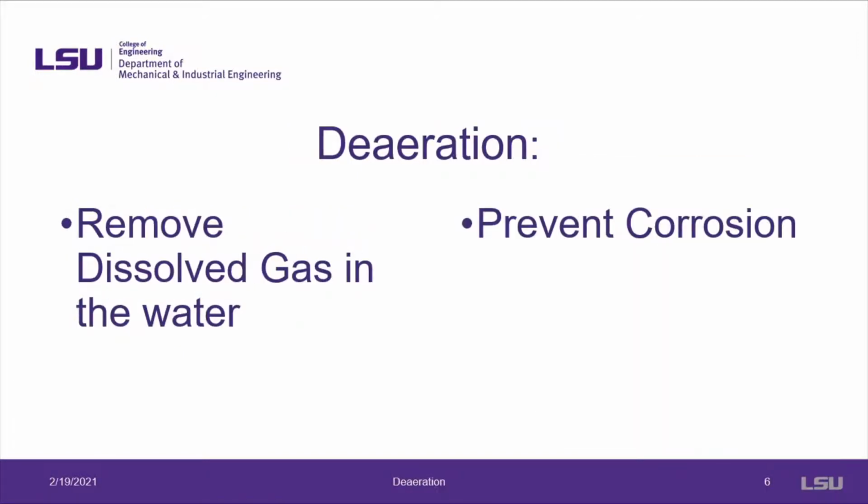The water leaving the demineralization system contains dissolved oxygen that is highly corrosive to the tubes of the boiler and the pipe connecting the boiler to the deaerator. Deaerators are used to remove this highly corrosive oxygen before it enters the boiler. The three main types of deaerators are tray type, spray type, and vacuum type.